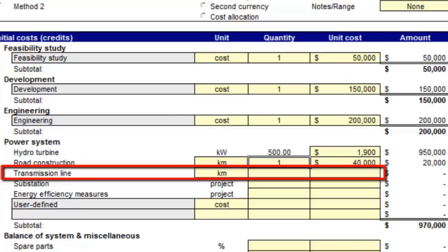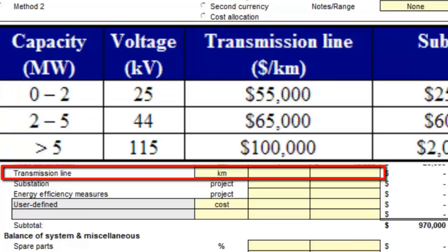The transmission line cost is site-specific and depends on the type, length, voltage, and location of the line, and the installation capacity of the power plant being deployed. The estimated transmission line and substation cost table provides an indication of the approximate costs involved, assuming reasonable access. These 2006 costs are representative of aerial lines in North America and should be adjusted based on site considerations. Underground lines are normally used to connect the system within an urban area, where the cost can be 2 to 4 times higher than an equivalent aerial line.